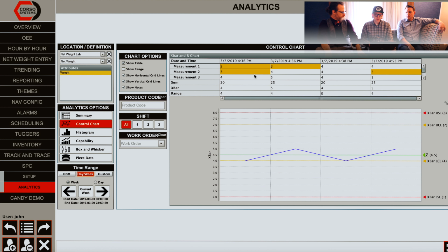Absolutely, yes. It's all about being able to identify issues within production as quick as possible. Like Alex was kind of pointing to, if we're going to create 1 million of a specific part, we want to be continuously checking to ensure that we are within dimensional ranges and doing visual tests. So say if these were molded parts, we want to make sure that we're not seeing an excess amount of flash or short shots in parts. So it's all about being able to identify issues within your process as quickly as possible so that we can not only avoid being behind on part creation, but reduce scrap considerably.